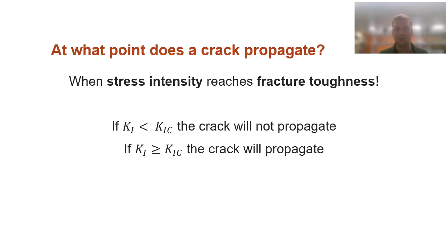And I would have accepted 2 answers here, but the main point is when your stress intensity, K1, exceeds your fracture toughness, K1C, the crack will propagate. I would have also accepted when the energy release rate exceeds the critical energy release rate. But the main takeaway is that cracks require a certain amount of something to continue, whether that's energy or stress.